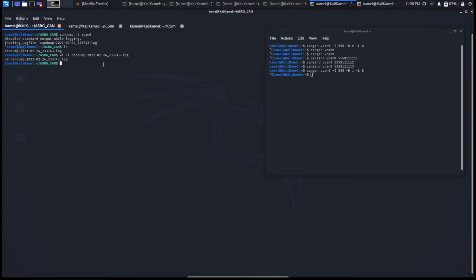What's inside those CAN messages? Great question. Well, let's think back to what exactly I did. I used a CANgen command with the arbitration ID set to 555, the data set to increment, and the length fixed to 8. So I'm going to assume that this CANgen process sent out the data 0, 1, 2, 3, 4, 5, 6 until it had reached 70 messages. That's just the coincidence of when I happened to stop the process. How are we going to actually see that?